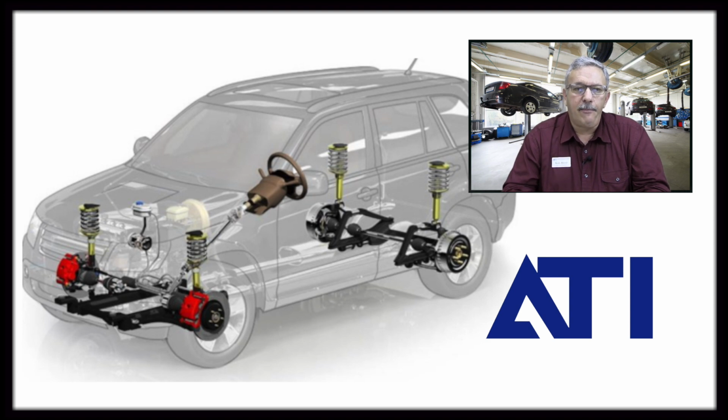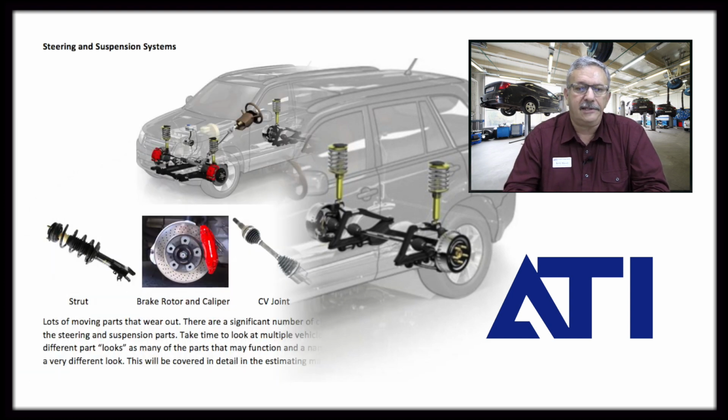So it's really important for you to look at the VIN number and identify what's required for that particular car. Obviously, as you get more skilled in this, you'll be able to identify these things just on sight. But some of the things that we have here, we've got to know struts and what struts do, and what we need to do if they're repairable. Can we just repair the strut tube? All those kinds of things.